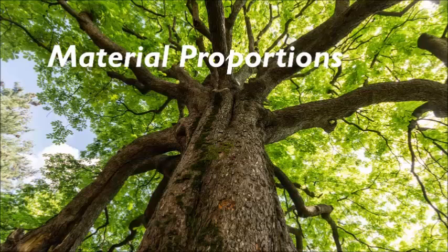So maybe you can get about 3 or 4 feet wide and have it unsupported in the middle. But if you keep increasing that size and say, well, now I want it to be 8 feet between the supports, then that material, based on its thickness and its material properties, would probably just crack or collapse under its own weight. So it would need to be supported at intermediate points along its length.